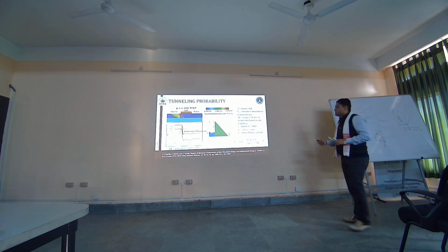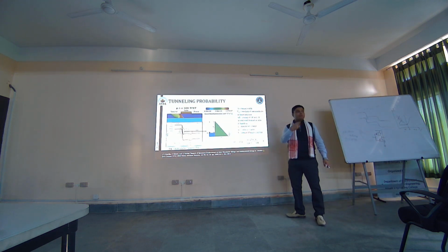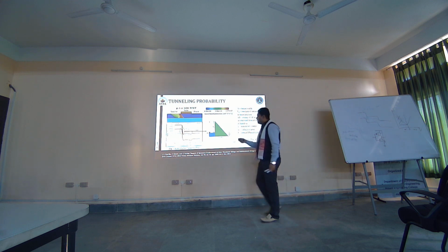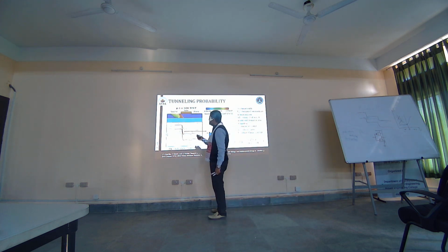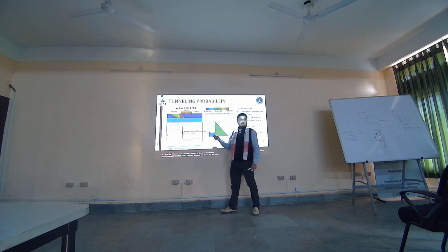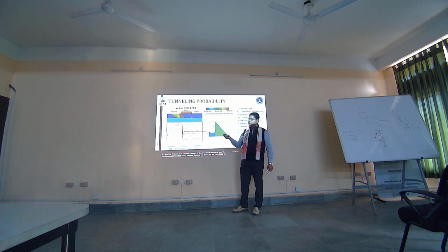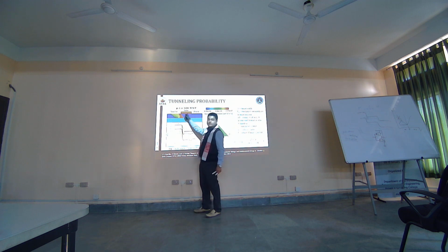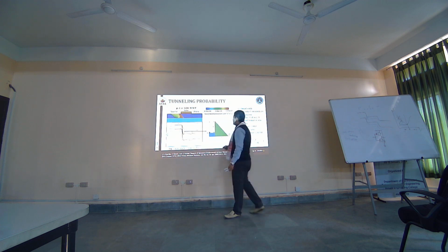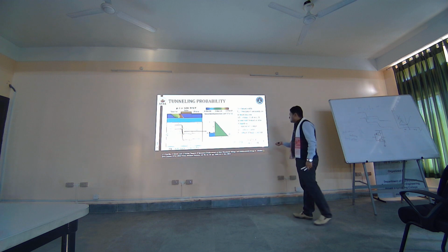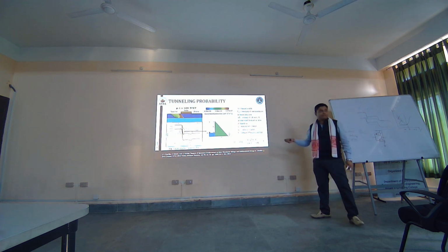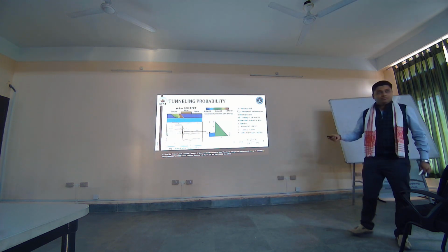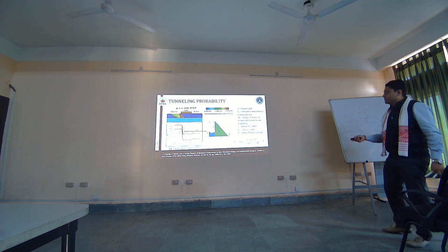Yeah, so this is some basics about tunneling which we have already covered. So as you can see, you can have this tunneling here at the junction, which is the highest. Okay, the red portion is the highest BTBT. Therefore, as I have said, you can shrink your gate up to a certain distance, right? Because your main region is here, so you can comfortably shrink your gate. Okay, and this is your expression for tunneling probability, which is the WKB expression. So I think this does not need any mention.